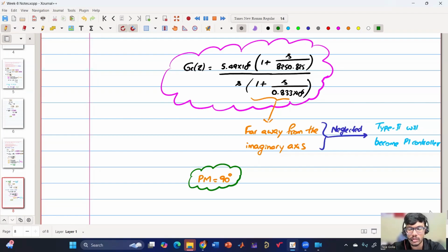Sir, typically for a system, is it preferred to have high DC gain or lower DC gain, or is it purely just to set the phase margin where we want it, sir? The DC gain of the controller. Yes, sir. It is not like preferable, but too much gain may be practically not implementable.